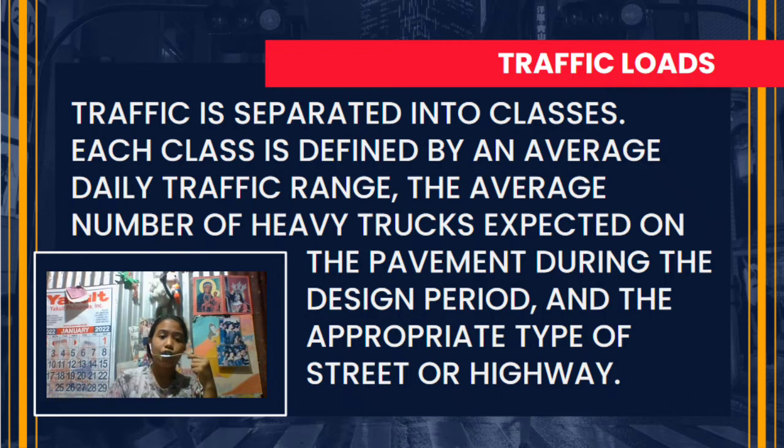Class 4 is medium, up to 4,500 autos per day, 700,000 to 1,500,000 trucks expected during design period. Urban minor arterial and light industrial streets, rural major collector and minor arterial highways, industrial lots, truck stalls, bus driveways and loading zones, airports, 30,000 pounds maximum gross weight.